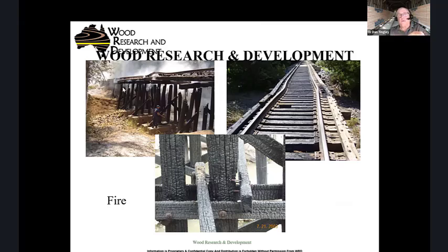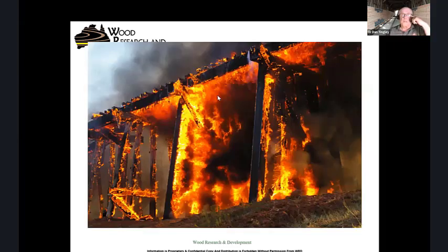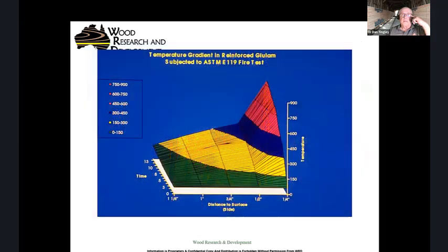Because in that decayed wood, the ignition point is dropped, that temperature is dropped, it ignites. Secondly, where all the verticals are, that's where the decay has gotten in there because of allowance of water in. And that's what engineers often call dry rot, which is a misnomer, there's no such thing as dry rot, that's what's burning here in these bridges. So fire resistance ratings are really about decay ratings. And that's how we use it.